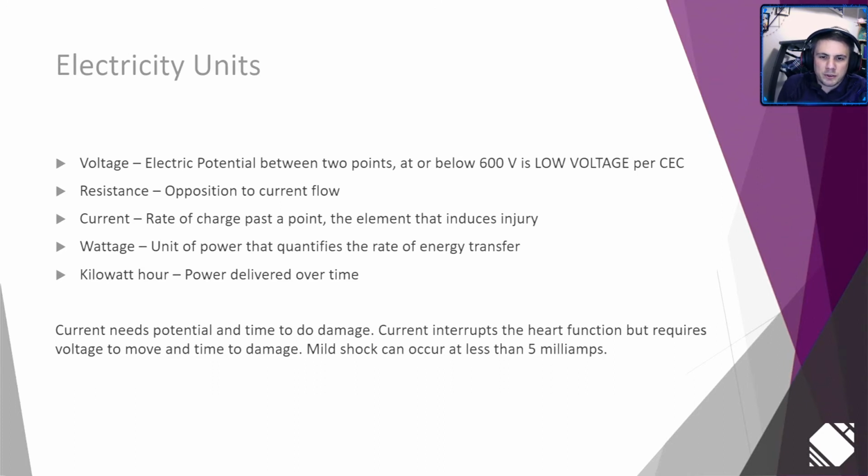People are protected by things like an AFCI that we talked about a couple of lectures ago. It goes in a bedroom to protect against arcs that can generate fires, whereas a GFCI is protecting against a ground fault. Water shorts from ground to line to ground, or somebody touches line while they're touching ground and gets shock. GFCI protects a person in that situation.